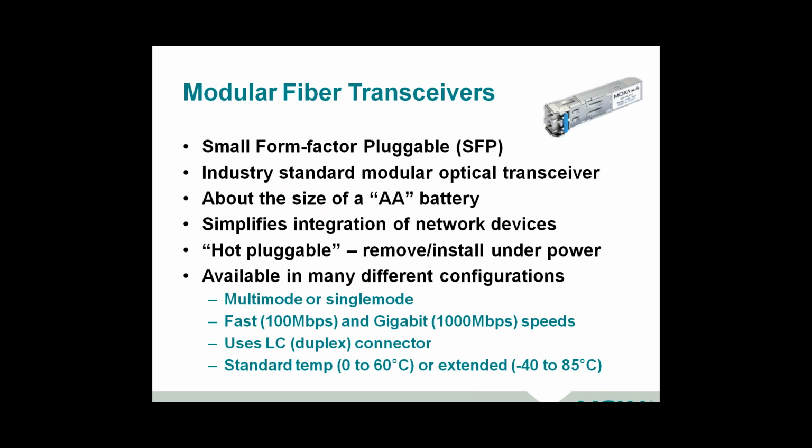If you'd like a little more flexibility and a little more design capability in your actual deployment, there's this technology called a small form factor pluggable, say that three times quick, it's a mouthful, SFP module. And these are really cool because it gives you an industry standard architecture. This is another example where multiple vendor organizations came together and came out with a standard. And this has been hardened for industrial applications. It's about the size of a AA battery, and basically it plugs into a slot in your switch or your media converter and gives you that copper to fiber capability. It's also hot pluggable, which is kind of nice.